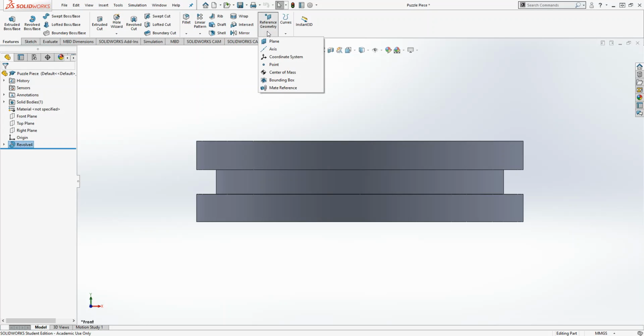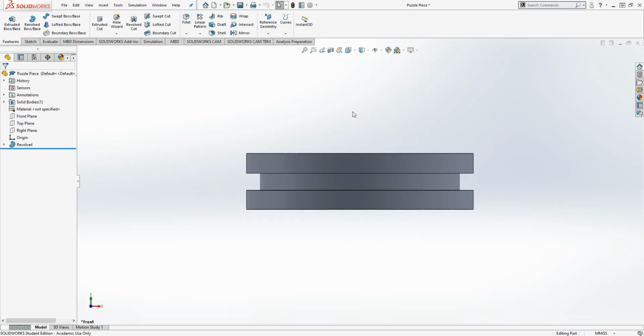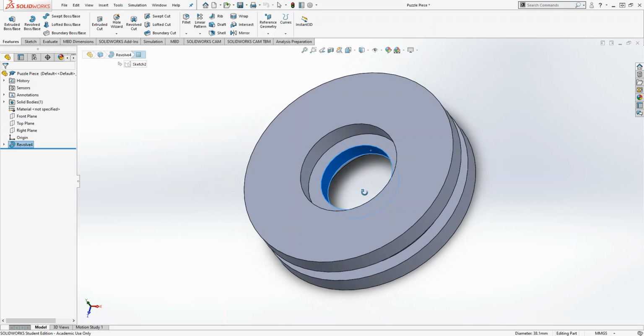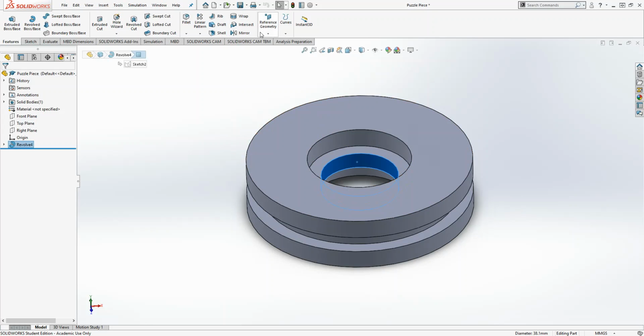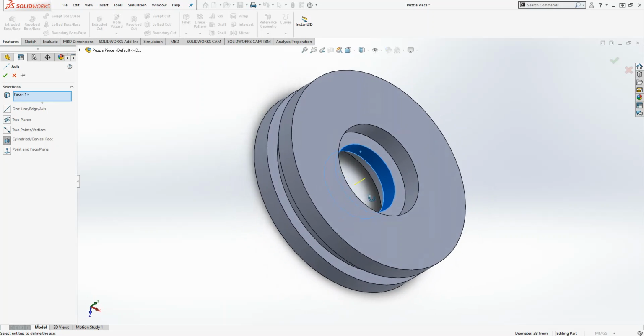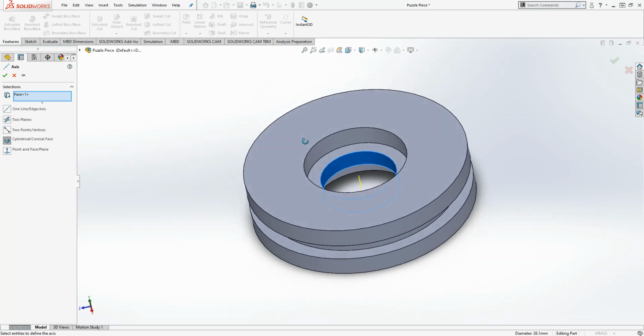There's a lot of different options. Now if I go ahead and reset the directions, I'll go to the front part of the sketch. We have this, and it's very simple. But one interesting thing is that you can also do revolving cuts on your parts. So now that we have a 3D space, we can actually define something called reference geometry. Now I can add in planes, axes, coordinate systems, all sorts of stuff, or even the center of mass in my part.